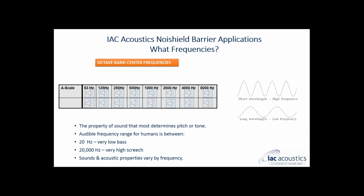When we're evaluating the design of the screen and the materials we're going to use to construct the screen, we have to take a look at the acoustic properties of these materials at a range of different frequencies. And to illustrate what some of these frequencies sound like, I'll play a couple of clips here as well. A relatively high-pitched sound, around 8,000 hertz, would sound like this. A much lower pitched sound, around 63 hertz, would sound like this. We can hear the entire range of frequencies in between.